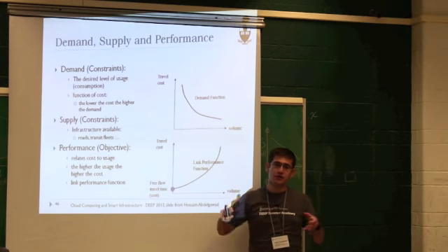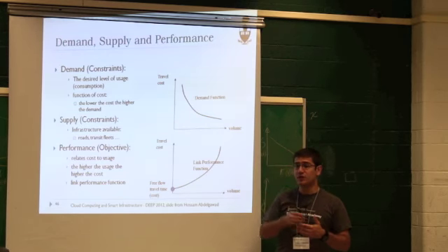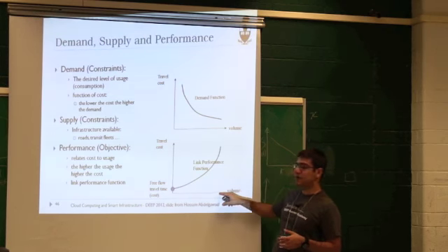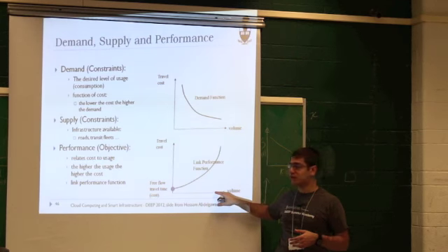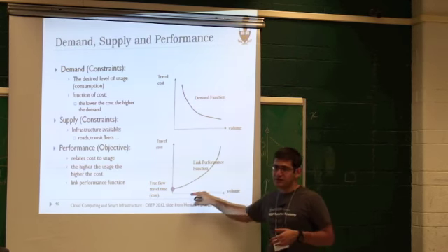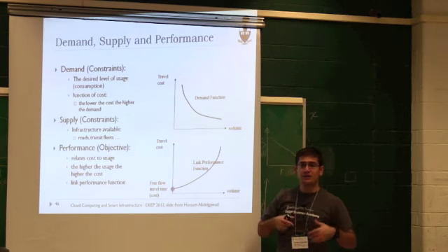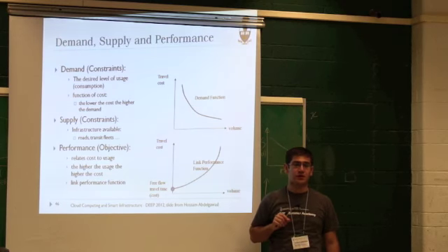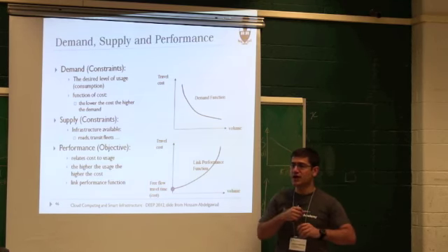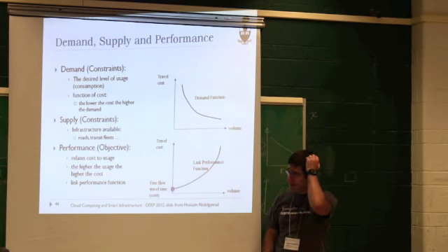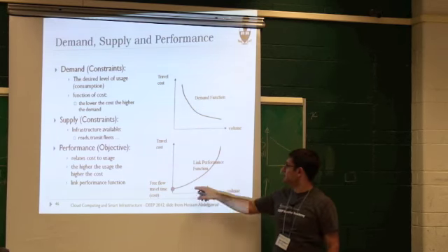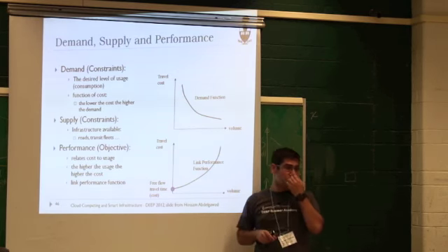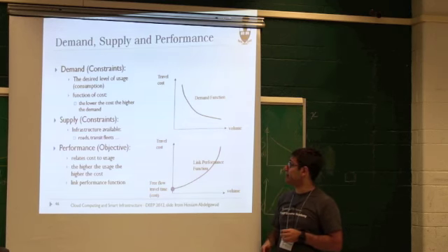By waiting a short amount of time at the ramp before coming out to the highway, we're limiting increasing the volume here. So we will be staying towards the left, and when they actually go onto the highway, things are far better for them. However, if we let everyone onto the highway, which is currently the case, in Toronto at least, then you have huge congestion because everyone is going to suffer with a long travel time.